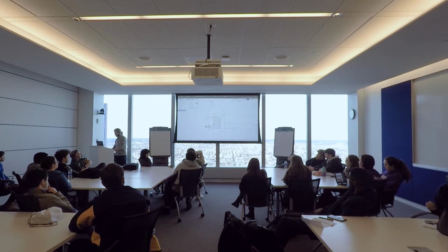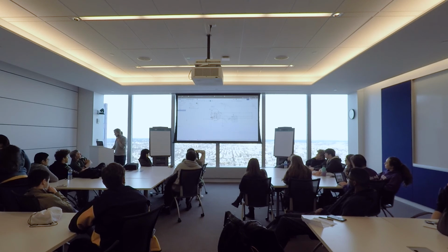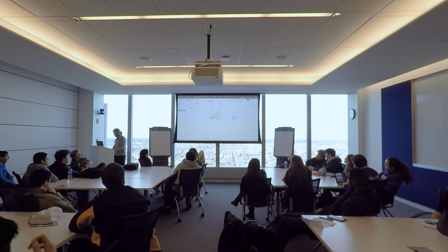We're going to do a circular pattern, which in Onshape is a bit weird. You have to click and drag. Circular pattern here. And then I want to make it just 2 times. And I want to change the angle until it just is within the robot. That's all I really care about. And we're going to do that.